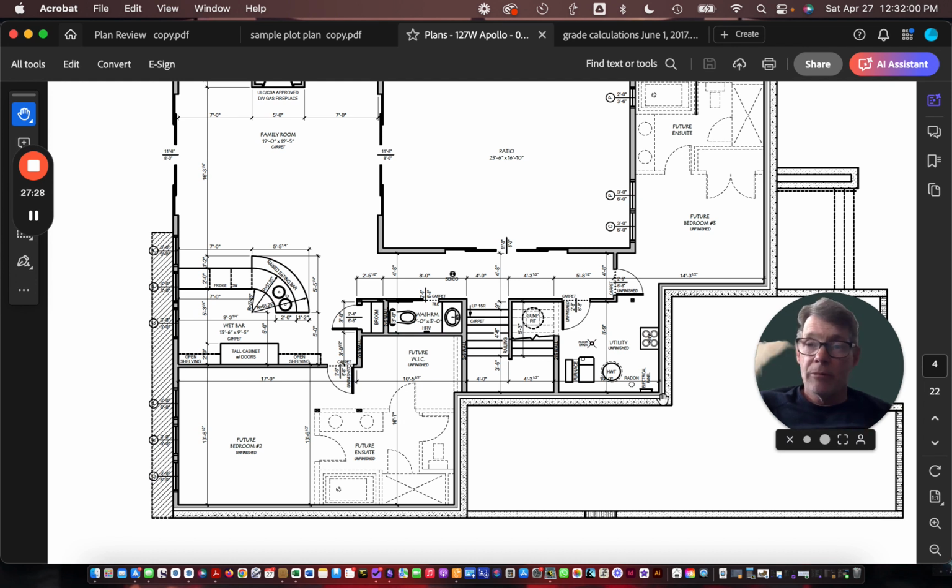Again, Grandpa's house probably had a 60 amp service because he's just plugging in a toaster. And then for the longest time, 100 amp was a residential standard. And still is in some locations, smaller houses. A bigger home like this, that may not be enough. So pretty sure we have 200 amps here. The reason for that is it's a bigger house, we have air conditioning, we got other features that need more power. And as we move into electric vehicles, having a little more amperage is probably also going to be useful if you've got a charging bay in your garage for your electric car.